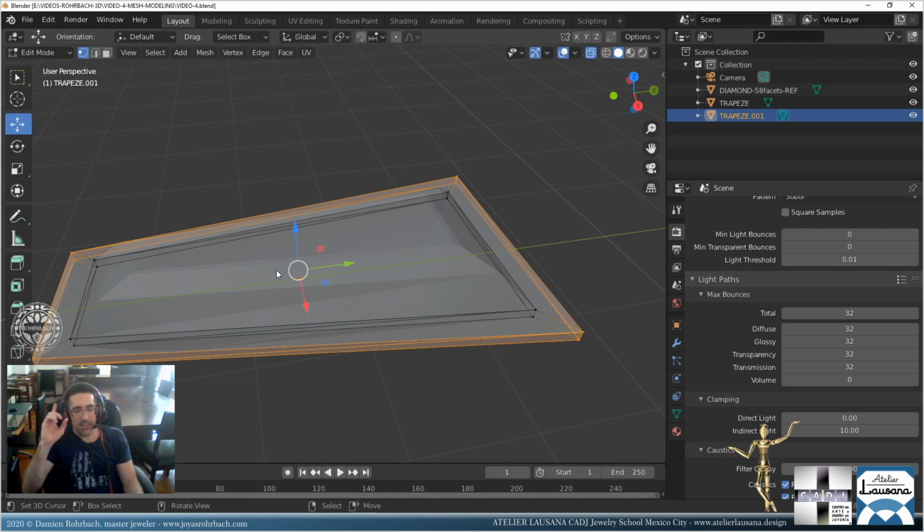It's not exactly so easy to achieve that in real life from a 3D model for a very simple reason. The printer is going to make somewhere, somehow, sooner or later, a kind of shrinkage. It's going to shrink somehow or expand somehow, depends on the type of resin you have, the type of machine you have. Even very expensive industrial machines, somewhere, somehow, sooner or later, are going to make a kind of deformation.